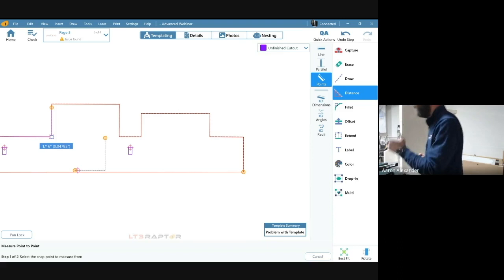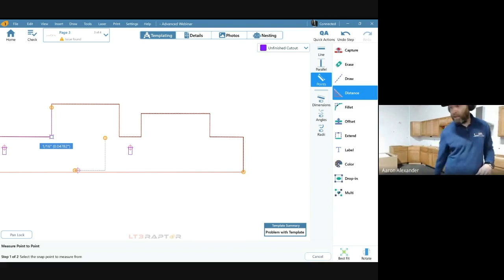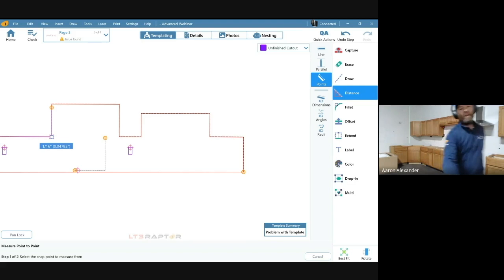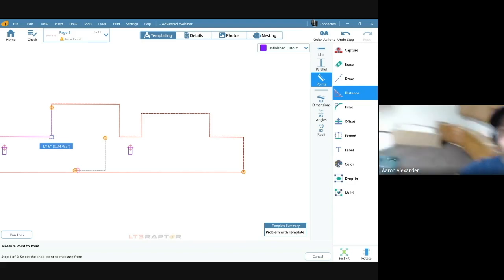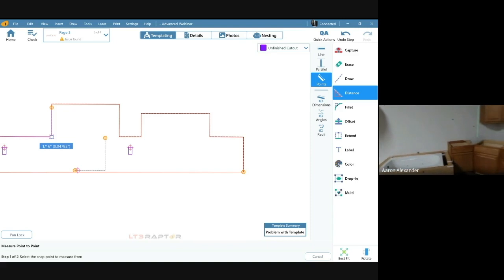Okay. Anthony's another one of our trainers, very experienced templater. And he's saying he uses the 360 laser to get a common line on all walls, to get seams at the same height. So you could shoot that laser like I got my laser. The thing's over there in the room, but it's hitting all the way over here. So that's what he's talking about, where we got that green laser line on both walls. If you leave that up there the whole time, you can shoot that on each one of these walls, and then you can align them in 2D space on the same page based off of that level line. Great tip there, Anthony.